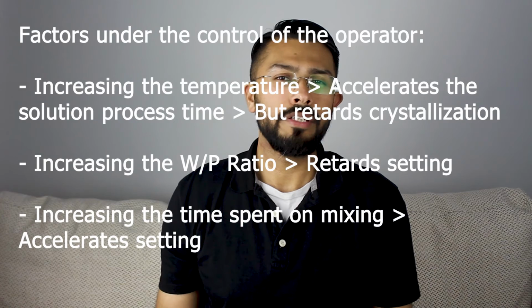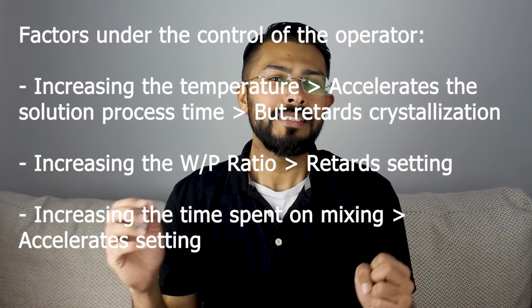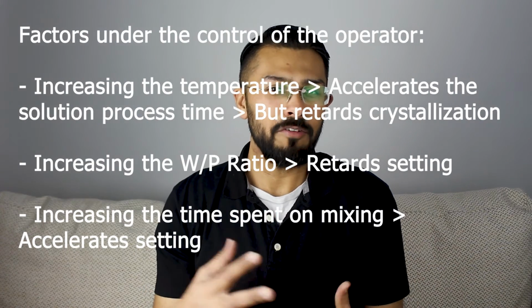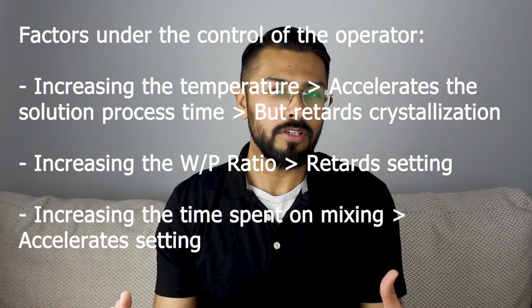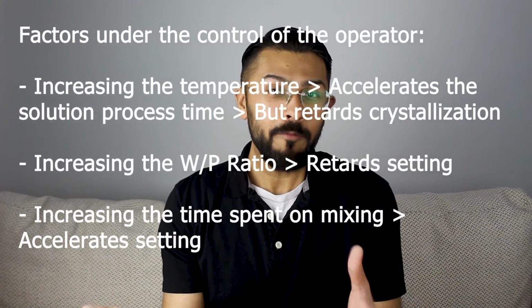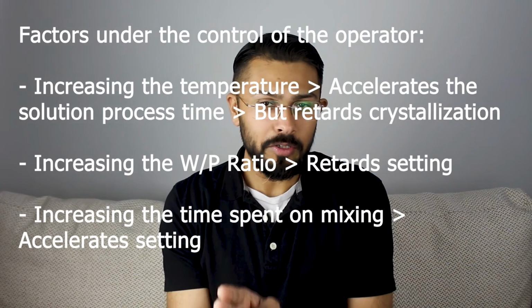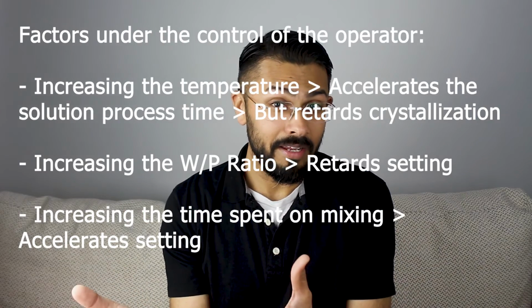Surprisingly, temperature variation has little effect on the setting times of gypsum products. This is due to the fact that the setting involves a dissolution of one sparingly soluble salt, which is calcium sulfate hemihydrate, followed by crystallization of another, which is calcium sulfate dihydrate.